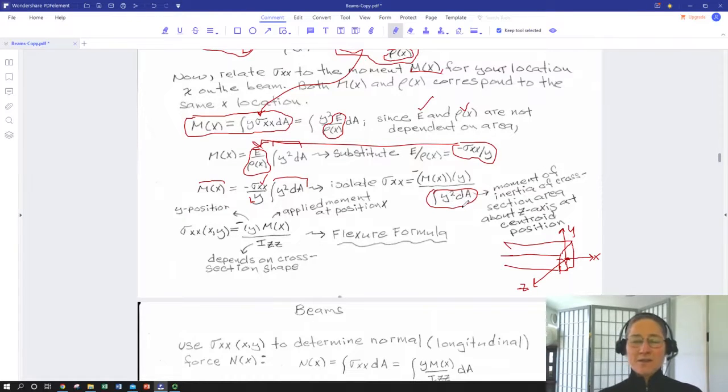So we're back to the definition of centroid. So this is IZZ. And if you remember work from your dynamics class, perhaps, where that was used for some rotational calculations, this is entirely dependent on geometry. So we can basically calculate that integral for any geometry. There's no mass dependence at this point. This is all about geometry and stiffness. So we don't have a density function. So rho here was radius of curvature, not density.